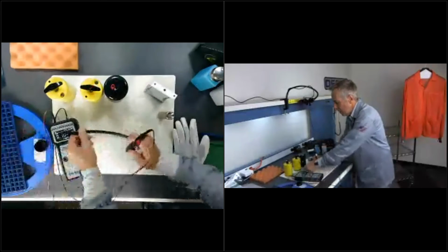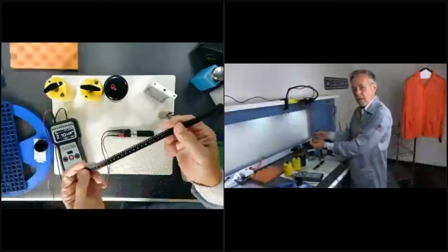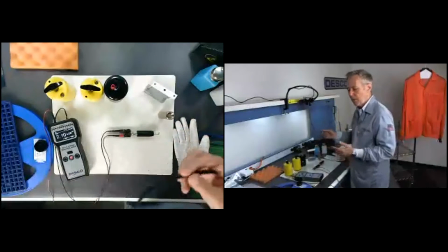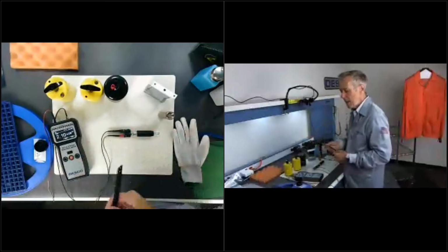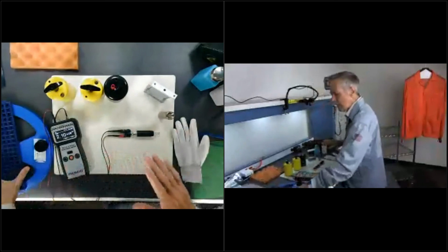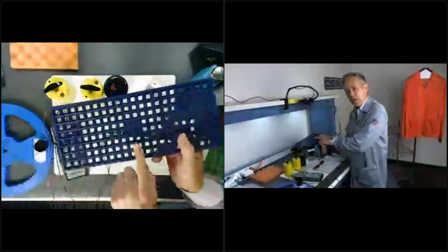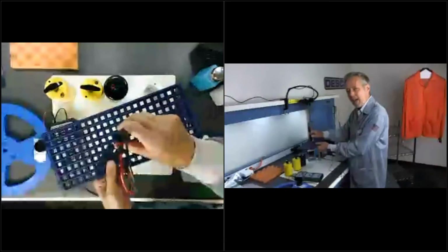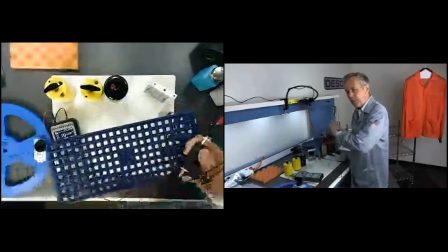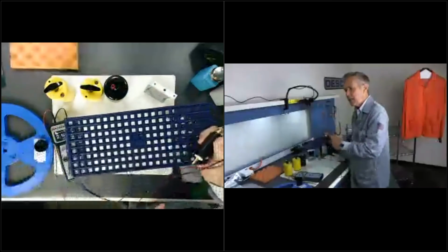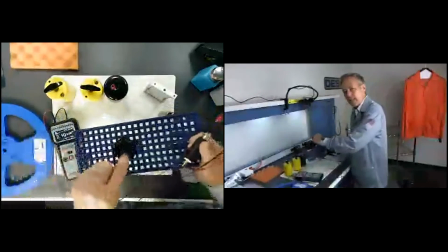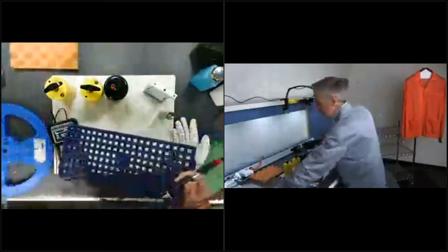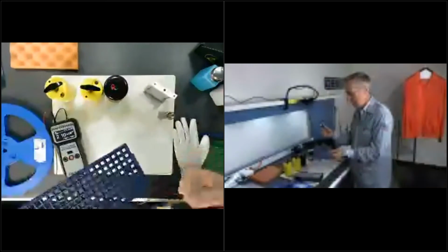So that would let me know, obviously there's no reaching hand on this. There's nothing that says ESD safe. So I want to use these types of tools to verify that it is what the manufacturer says it is. I'm not going to test everything here, but this would be another perfect example of what to use a 2-point probe for. Testing down inside a cavity, because not everything is just a planar surface. Sometimes there's peaks and valleys, or, like I said, inside this cup, where I might have to get down inside something I want to test with this tester.